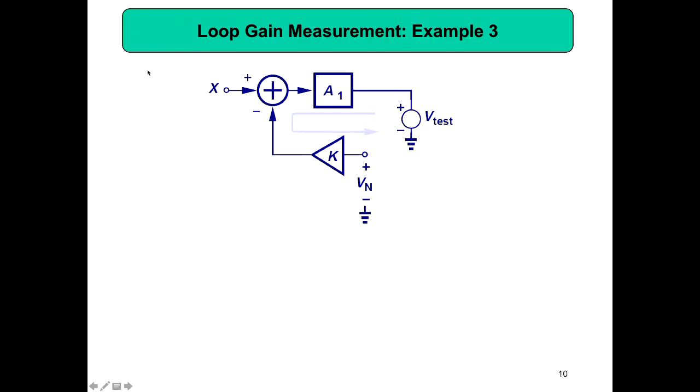So then this one will not work, because what you are trying to do is connect signal to the output, you are pumping signal here as an input. Your output now you are using as an input, and then you are trying to use it, but you can't. Signal will not go from output to input. So this way you can't get the loop gain. Incorrect calculation of loop gain, because this is logically not possible.